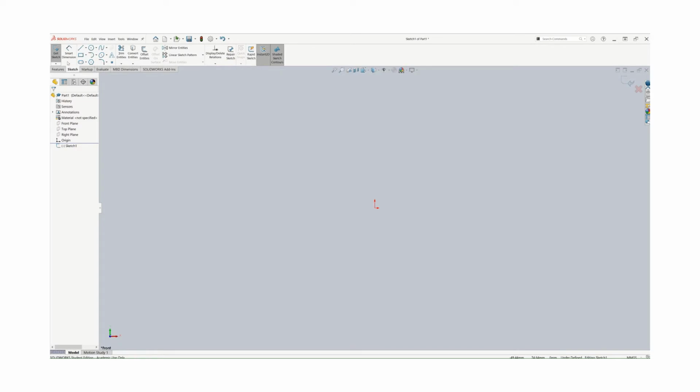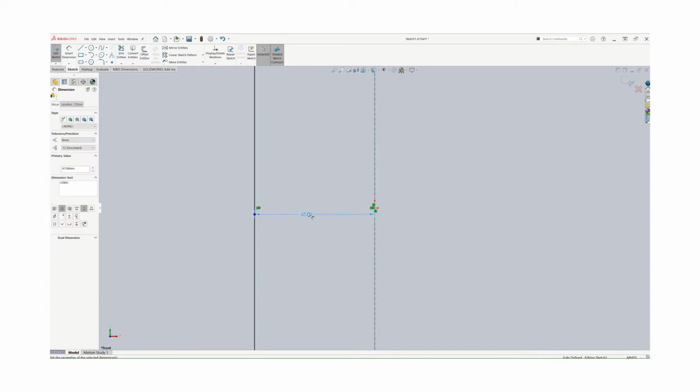In this case, I'm going to draw a center line, and for convenience, I will just draw a vertical infinite length line. I choose the origin of the coordinates. It creates one center line. And as I said, I will offset this line, going in the other direction, so reverse. And I will put the dimension, 134 over 2, that's 67, which is basically one of the lines to the outer edge that we have. Sometimes if you have the dimensions, it bothers me, or it would bother you also, so I will delete that one.